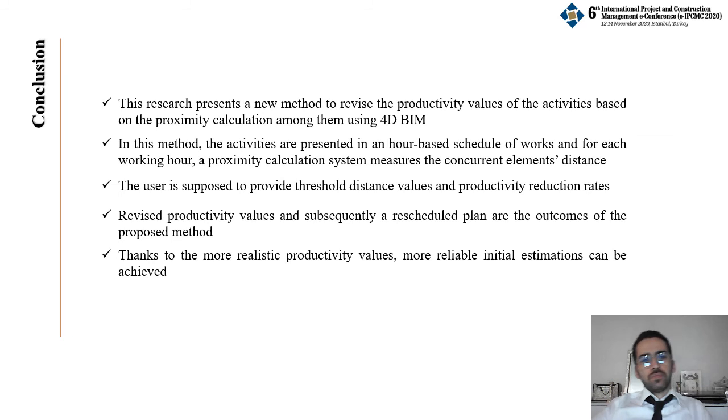To sum up, this research presents a new method and approach for revision of the productivity values. In this method, the activities are presented in an hour-based schedule of works, and for each working hour, a proximity calculation system measures the concurrent element distance by using 4D BIM.